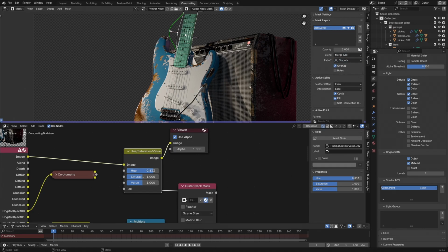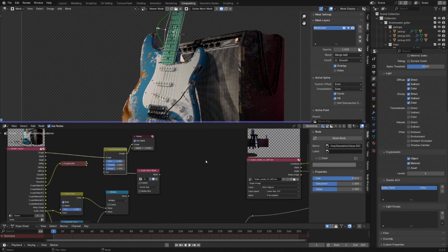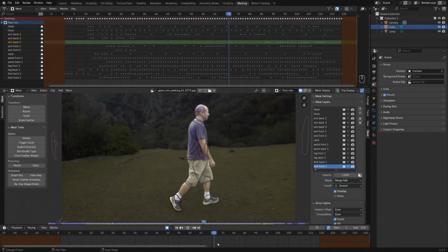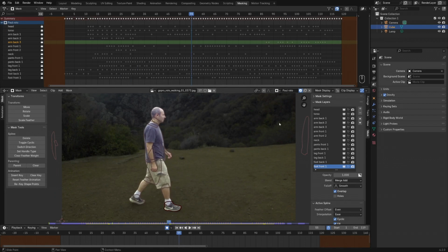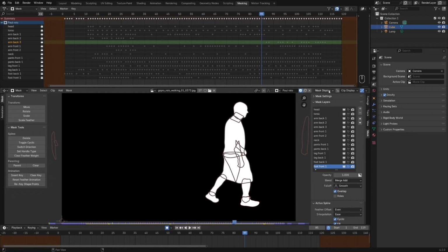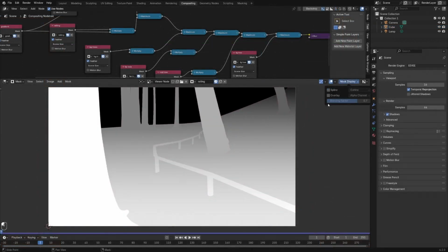Like I said, this is a big topic deserving of its own course, and I really just want to introduce you to it here. Rotoscoping is, however, an essential compositing skill set. Some of the projects in my professional work have had literally hundreds of rotos in a single shot. You can create very detailed rotos to separate an object in the foreground, and you can even create things from scratch just using rotoscoping, like glows, shadows, even a fake Z-depth pass.